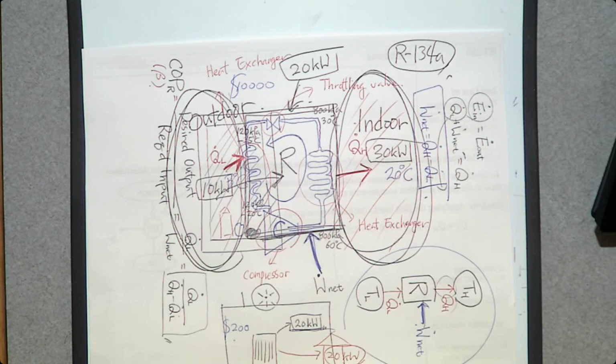If the outside temperature is above 5 degrees Celsius, like the winter in Texas, run the heat pump. If the temperature goes below this, then the heat pump is not that efficient, so run the conventional heater. That's how it works. Okay? Make sense? All right.